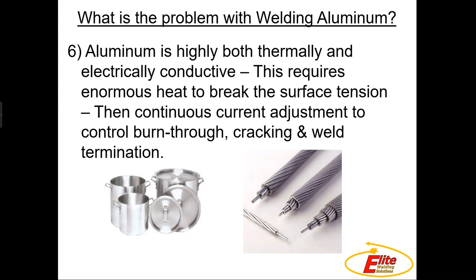And this type of conductivity, we can see it at home. If you look at your lawnmower at home, your lawnmower has an aluminum engine block. It's got fins in it. These fins are meant to drag heat away from the cylinders and to drag heat towards the outside edge. It increases the surface area. Fins increase the surface area, allowing more heat to move through it more efficiently.